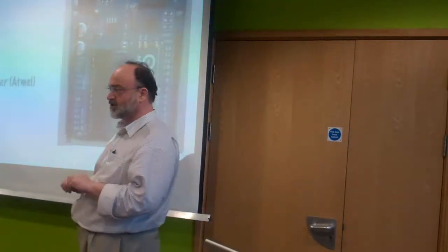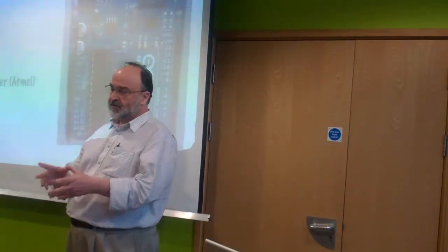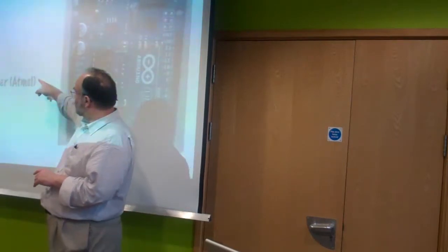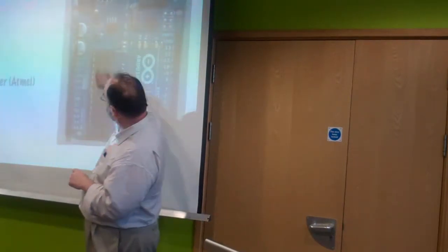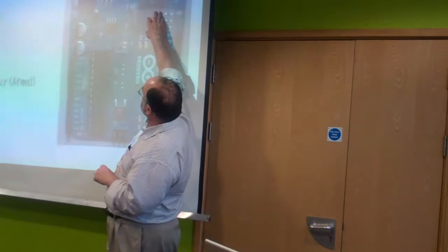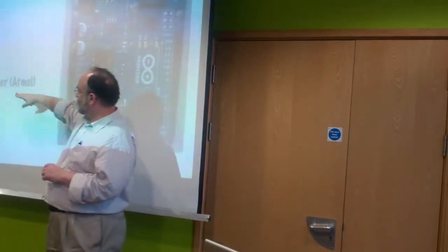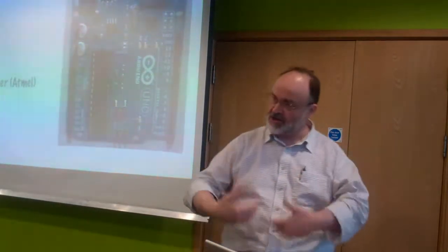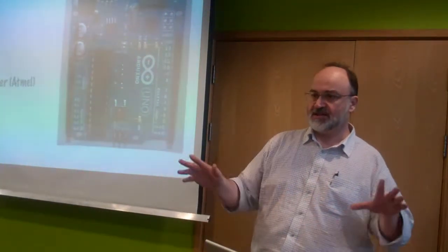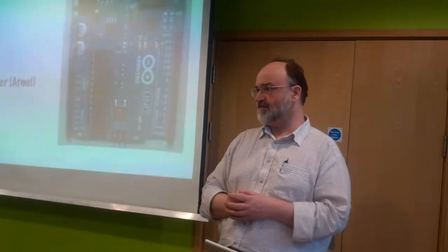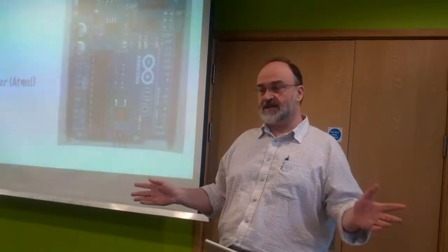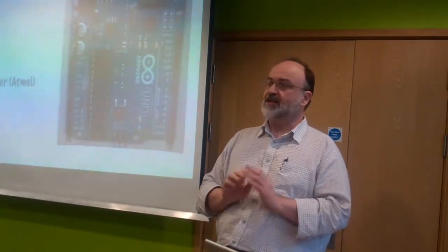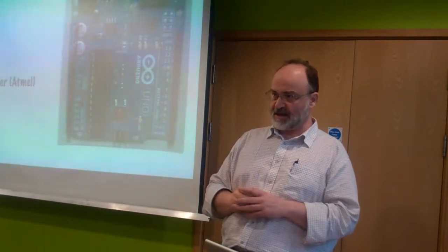It has unleashed an enormous number of people in this world. So it's based on a little microcontroller, the chip. It's got a USB interface, this bit up here. It's got an open source IDE and some extremely well done libraries, and under the covers is GCC, and all of the software and libraries are open source, and all of the PCB CAD is open source. The only thing that is protected in any way is the word Arduino, which is trademarked.